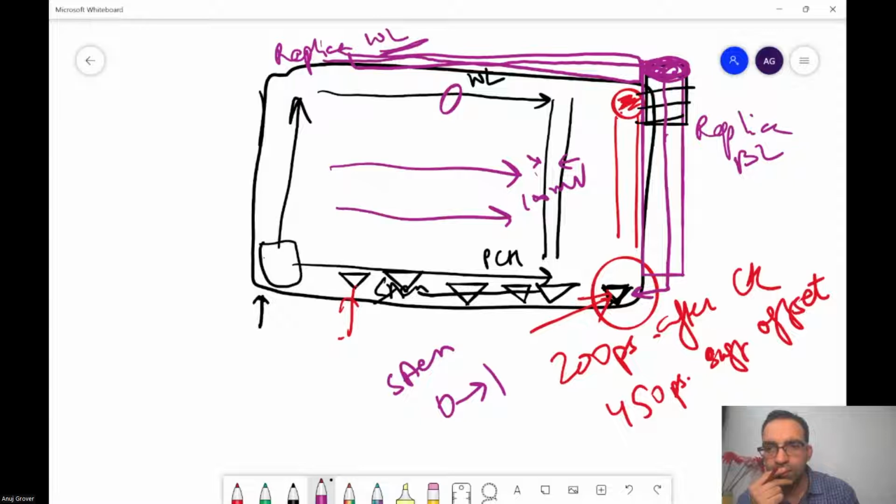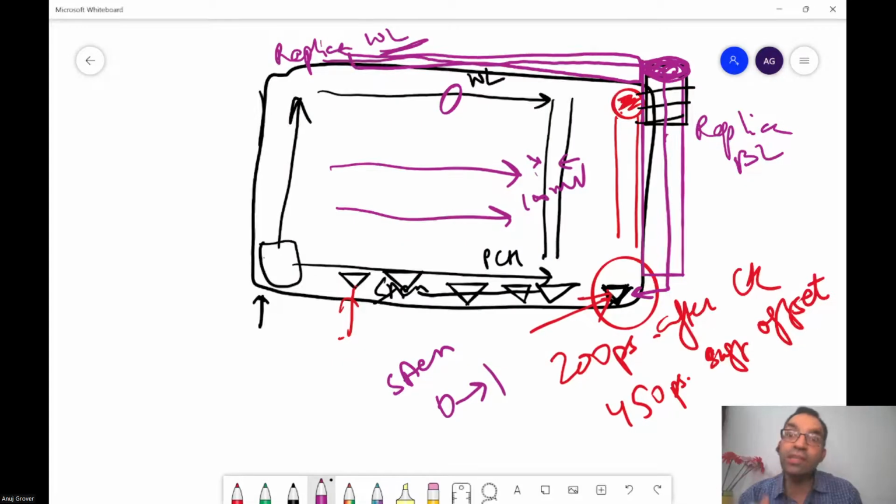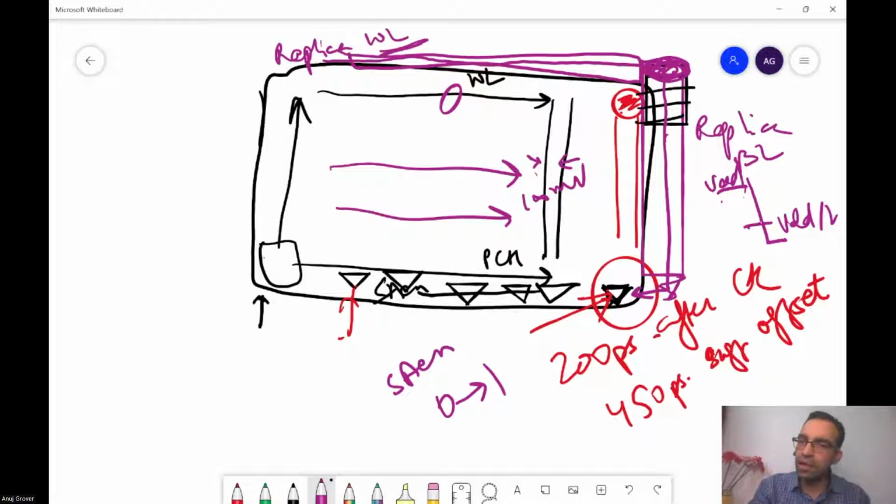Yes. Then how will you generate the digital signal? If you say I put a sense amplifier, then what will trigger that sense amplifier on the replica bit line? Cannot be done, no? It becomes a chicken and egg story. So only the replica bit line, you say, will discharge fully. It will go from VDD to almost 0, or let us say less than VDD by 2. So what happens? You put an inverter beneath it. As the replica bit line goes lower than VDD by 2, the inverter generates the SAEN signal.